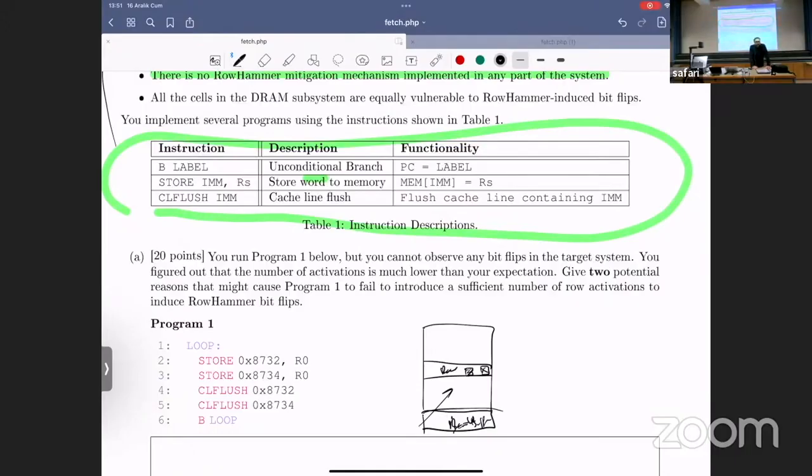What about the second reason? Similar to this, we can also have an address mapping that puts this second piece of data into another bank. In that case, as you know, each bank has its own row buffer. Once you access this address, for example, you will be accessing this row buffer. Once you access this address, you will be accessing this row buffer. So it's also, again, a lot of row buffer hits, and there's no hammering kind of access pattern going on.